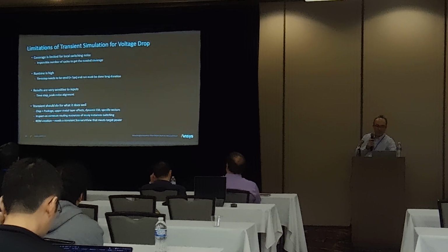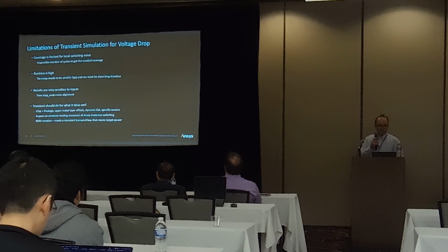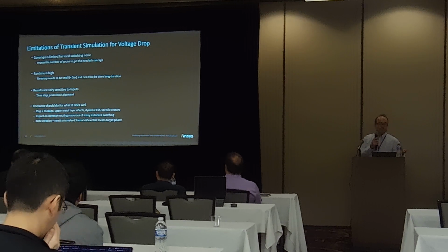We have a good solution, like SPICE, which every engineer has been using like a hammer on everything. We have been using transient simulation on many power integrity sign-offs because it gives us realistic, good results. It's trusted, the models that we feed in are validated, and we also have some silicon backup too. But the runtime is too high.